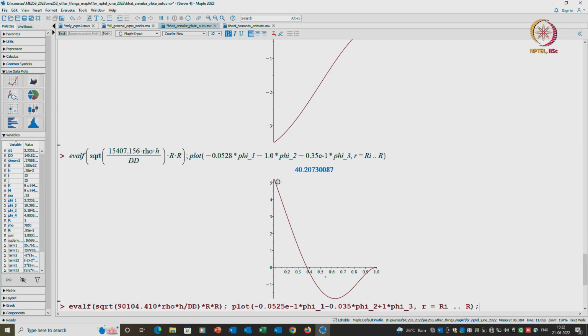Then this is the annular plate again. So the hole is below this value, and there is a node, and it finally reaches the edge. If we now rotate this shape about this vertical axis, it is an axisymmetric mode. Now, this will be a circular node line.